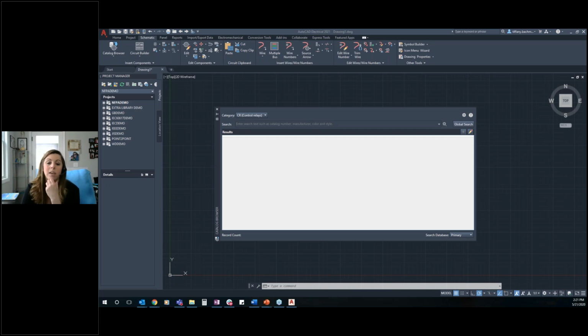shared network drives. Or like I said, if you're utilizing a Vault environment where you want to do it as opposed to it all just defaulting to the C drive. Do it from that initial install. And I'll even have people say, well, I've already installed it. Should I just have to go through all the manual path? No, uninstall it, create that deployment, reinstall. It'll be so much faster.